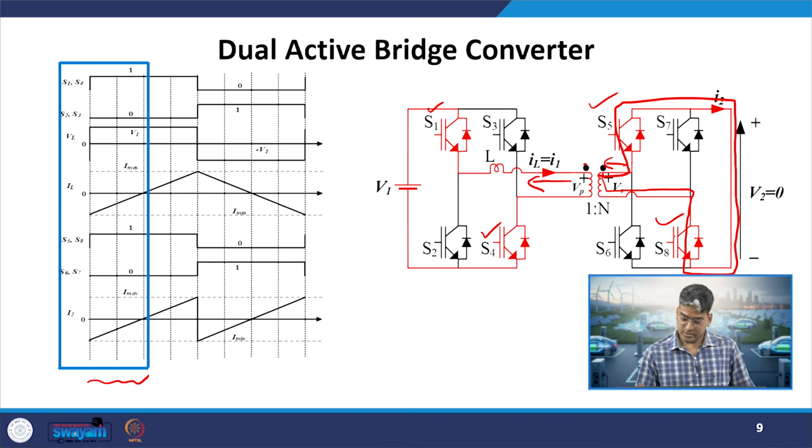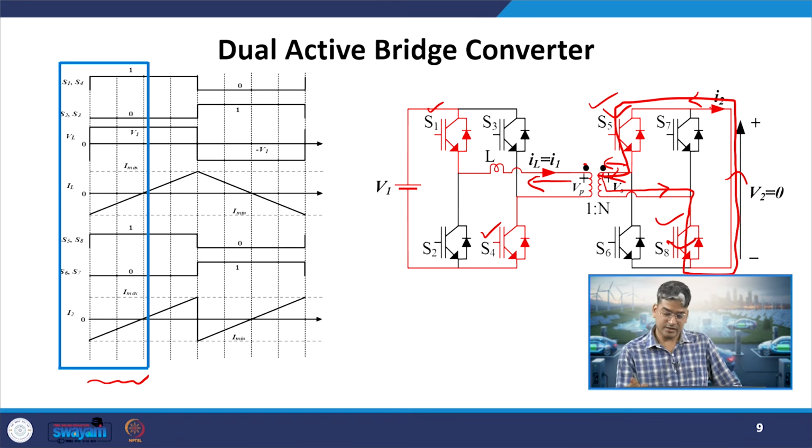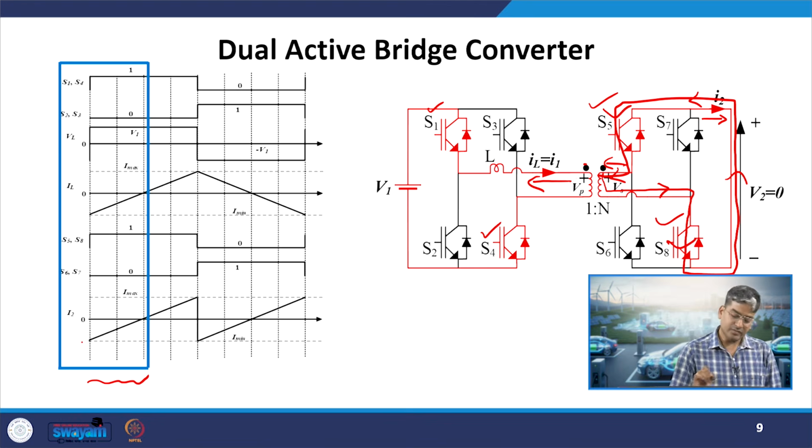Okay. So, here this is what the current will be. It flows through the IGBTs and returns to the secondary side transformer terminals. Okay. So, now if I see what is the current direction, it is negative because we have marked this as our measurement direction for I2, and now the current which is flowing is in the opposite direction of our measurement. So, I2 has become negative.